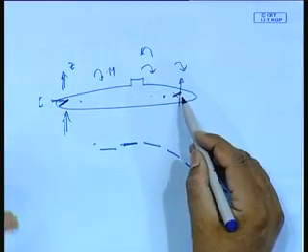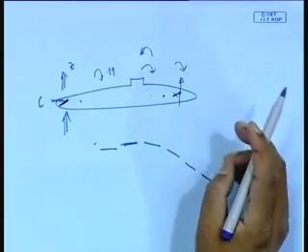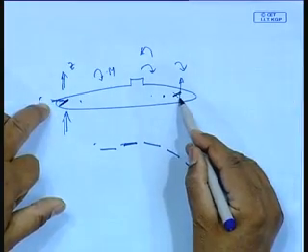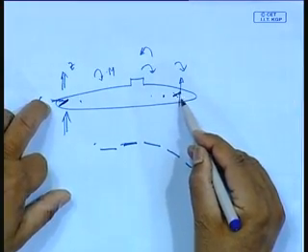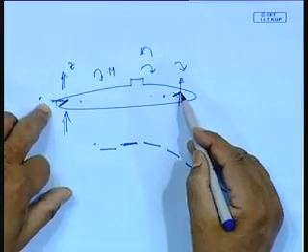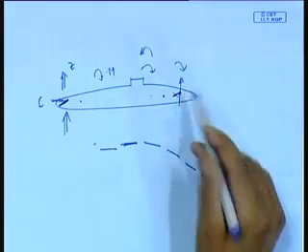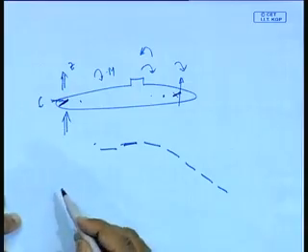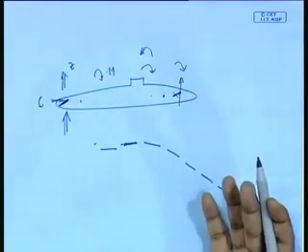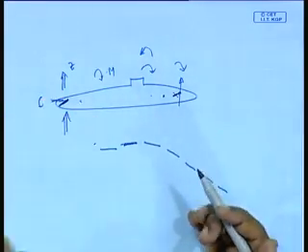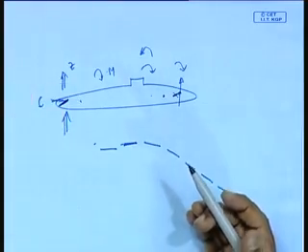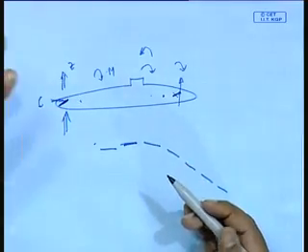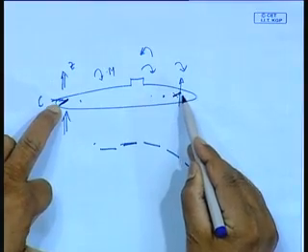But look at vehicles like torpedoes, AUVs, other vehicles, you do not have two. Why do you not have to? Because take an AUV, there is no human sitting there. So, even if it goes down at 60 degrees, you do not care. But in a submarine you have to control the trimming angle. You cannot go down from 50 meters to 300 meters at a 40 degree nose-down angle, then everybody is going to fall. So, therefore, you always have to control trim, and that you do with this.